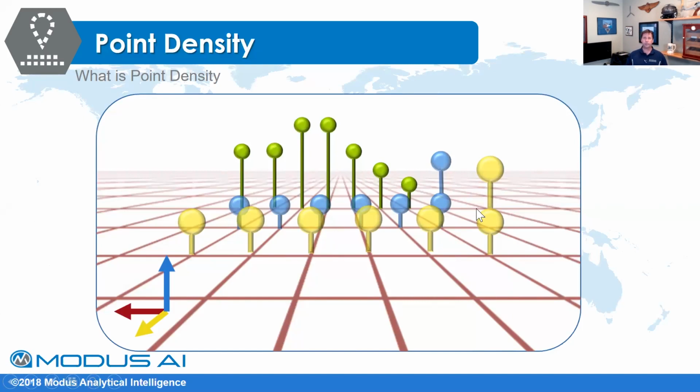Now for systems like a Velodyne or a Riegl, depending on what you're going to be using, you're going to be collecting somewhere between 200,000 to upwards around 700,000 points per second, maybe even up into the millions if you have dual return options. Each one of those points is going to have your three cardinals, so your X, your Y, your Z.